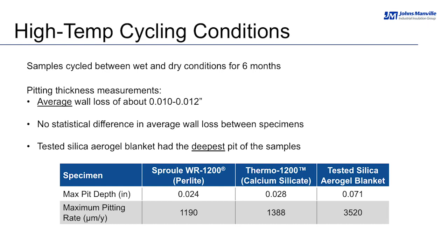Based on the test results of the different measurement techniques, SWRI calculated the pitting rate in microns per year for the 3 different pipes, and those are also shown in the table. So again, this 3-times difference between installations is very significant, as the deep pits are usually the points of failure and also the most difficult to detect areas of corrosion, again, as Juan Carlos mentioned. One thing I want to keep in mind, though, is that these results shown here in this application that we tested had no coating. It was a bare carbon steel metal. It was also exposed to 1500 ppm chloride and 900 degrees Fahrenheit. So, again, depending on the environment and application, these pitting rates will be different.